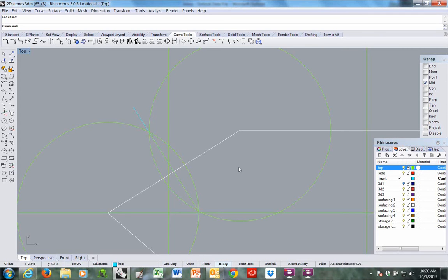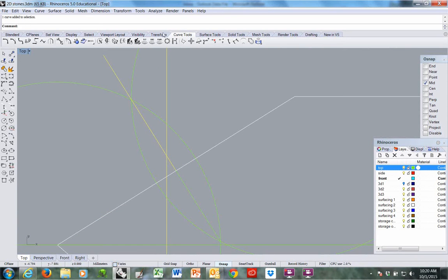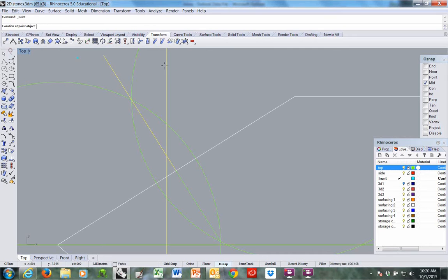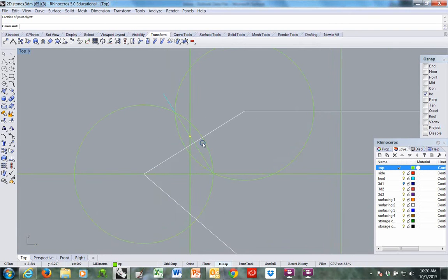And we can compare and see that they are the same line. So either method would work. What is critical is where these two meet, because this is our actual elevation line. Okay? Right here. That point is what we need. That's why we brought this information down, why we brought this information off of this plane at the midpoint.